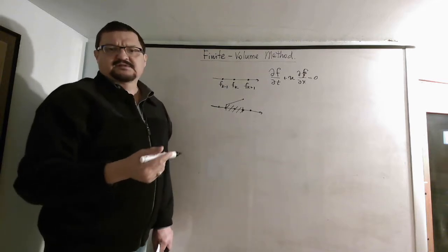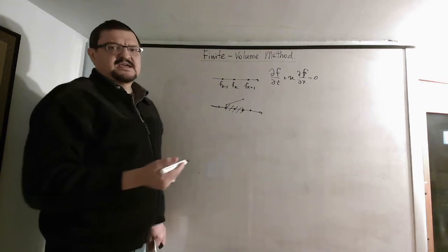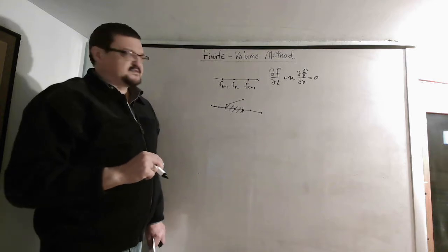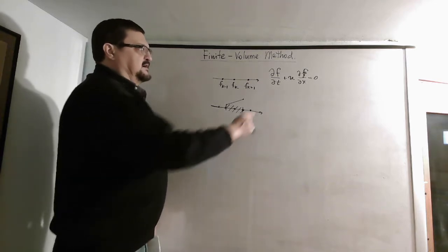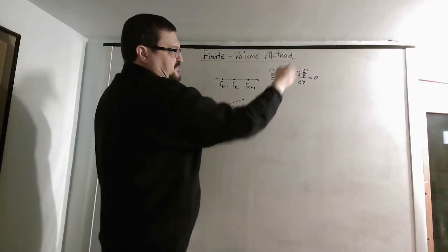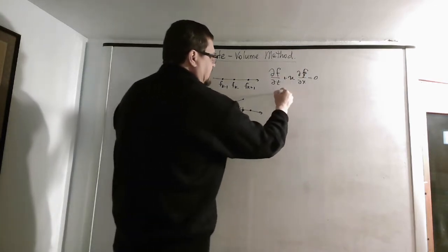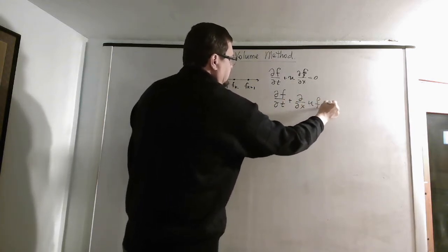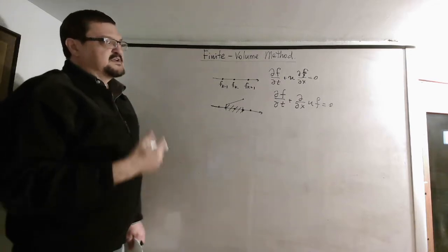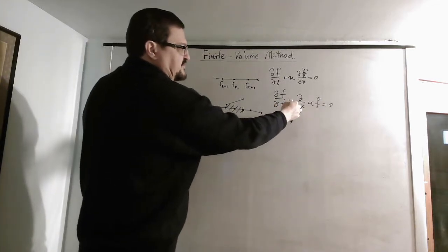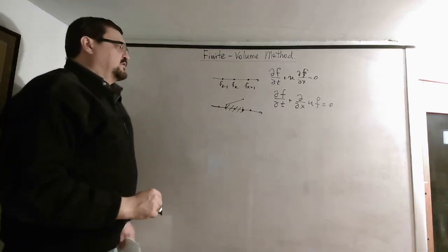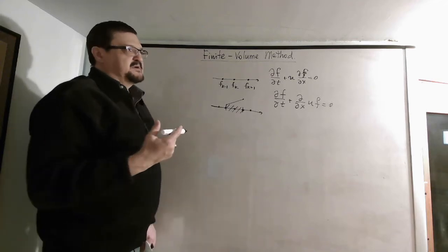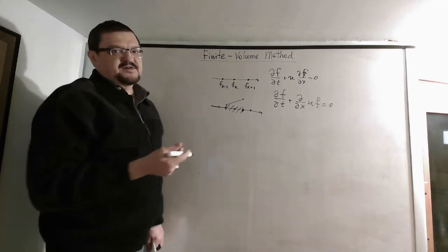When we talked in the last couple of lectures about conservation, we actually derived the equation in so-called flux form. And there the concept of fluxes appears. Here there are no fluxes, this is just advection or transport of some quantity. So if you wrote it like this, then it's a conceptually different framework, because now you have the derivative of some flux. So this is basically the basic conceptual difference between finite difference and finite volume.